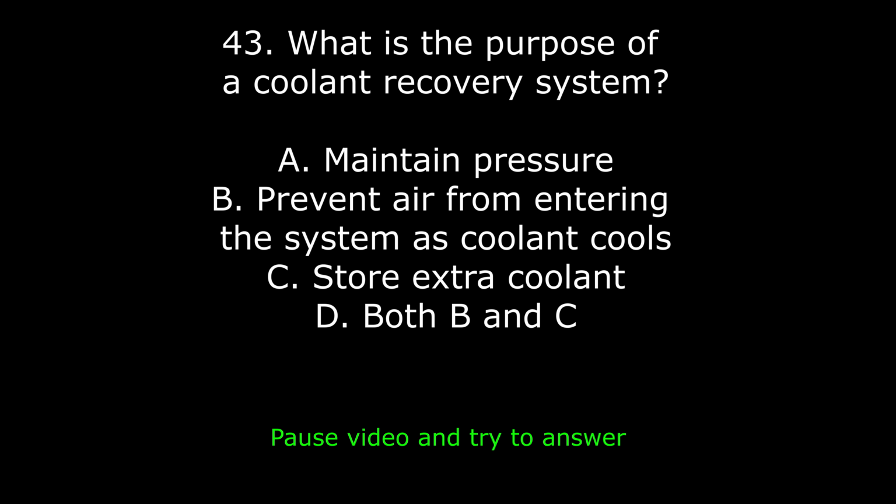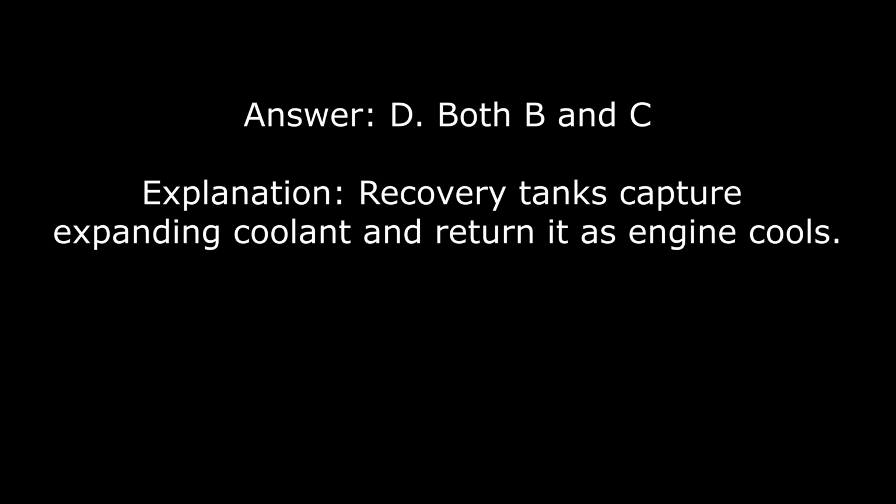43. What is the purpose of a coolant recovery system? A. Maintain pressure. B. Prevent air from entering the system as coolant cools. C. Store extra coolant. D. Both B and C. Answer: D. Both B and C. Explanation: recovery tanks capture expanding coolant and return it as engine cools.